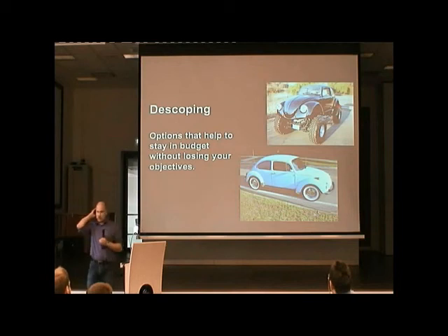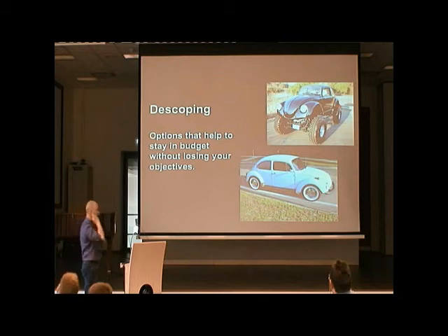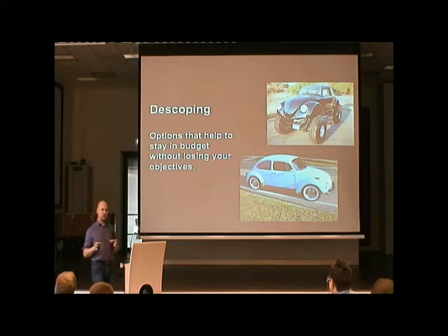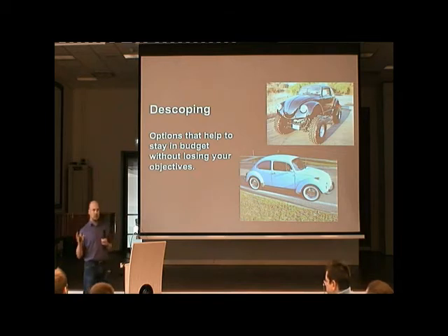Descoping. Something you should also take into account when designing your satellite is descoping. Descoping means that you should identify the parts of the mission which are absolutely crucial, without which you cannot do your mission. But there might also be nice-to-have parts, because we are not so often going to Mars or Venus orbit, and maybe even Moon orbit, and there might be a small instrument we can accommodate on this flight, just for nice extra science.